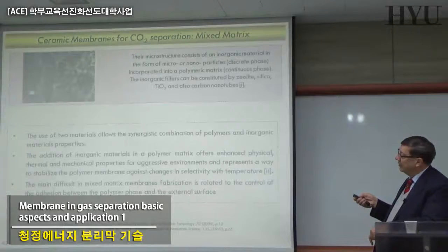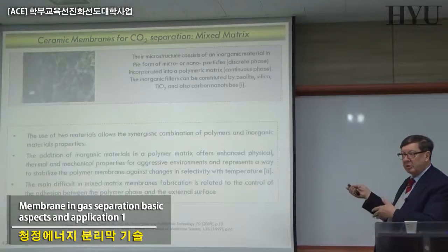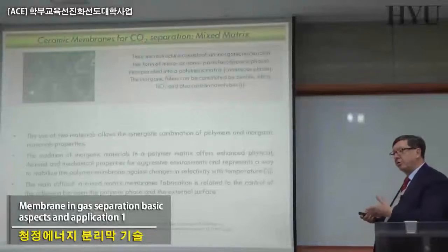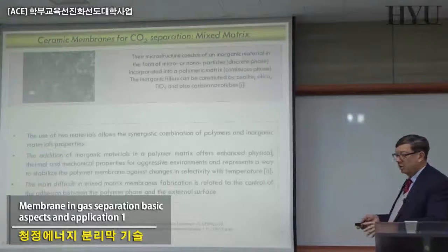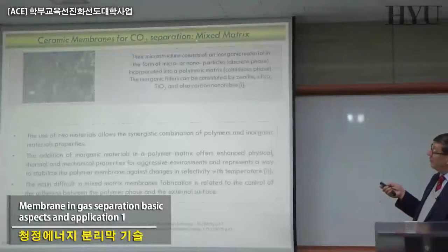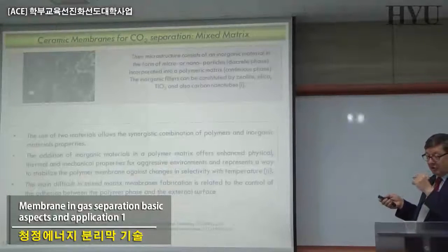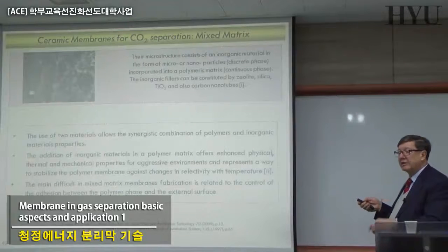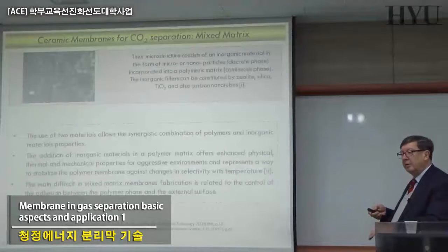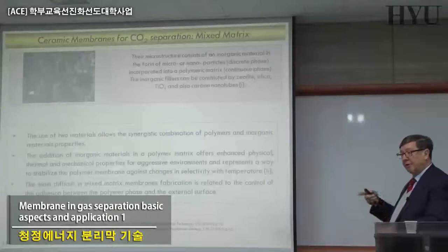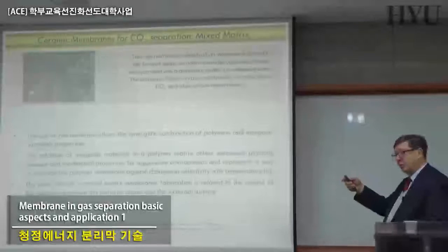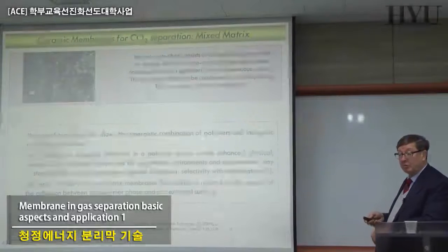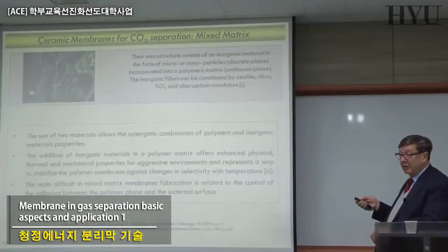for immobilizing titanium dioxide in ultrafiltration. That means polyether sulfone or polysulfone membranes as a pre-treatment to reverse osmosis. It is a big project in which a lot of people are involved, and they are just preparing this mixed matrix, not for gas separation, but just for taking profit of the catalytic activity of titanium dioxide that can destroy some organic present in the water that you have to send to reverse osmosis, and that can be one of the ways to improve the performance of the traditional ultrafiltration by adding titanium dioxide.